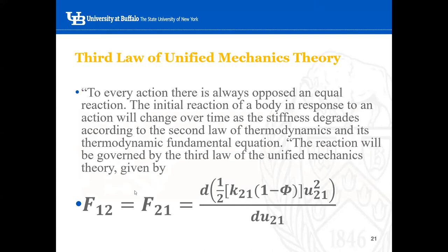And the third law of the unified mechanics theory, again, combines the third law of Newton and the second law of thermodynamics: to every action, there is always an opposed and equal reaction. The initial reaction of a body in response to an action will change over time as the stiffness degrades according to the second law of thermodynamics and its thermodynamic fundamental equation. The reaction will be governed by the third law of the unified mechanics theory.